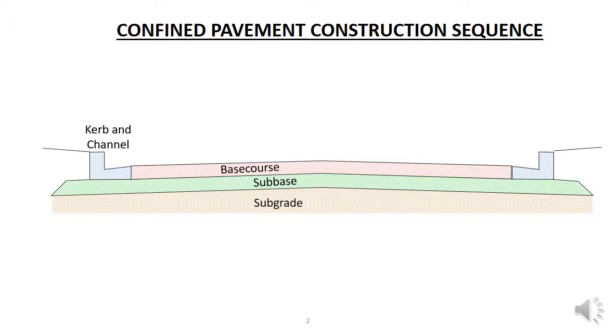The surface is then rolled with a static steel roller and pneumatic tired roller to provide secondary compaction to tighten up the road surface. The secondary compaction may be done in conjunction with a running course. The running course is an AP20 aggregate with significant fine sand content. The roller compacts and kneads the finer particles into the surface, filling any voids and locking the surface up better. Road traffic may be diverted over the surface to further aid the secondary compaction.